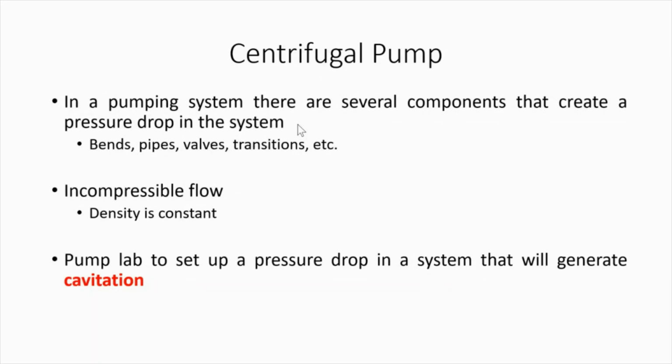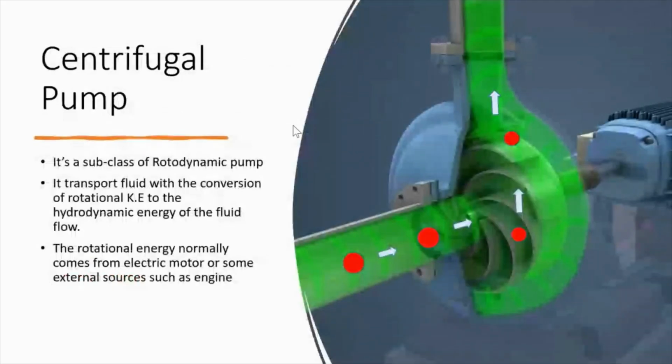before getting into that, I think Carlos has a question. He's asking, so the blades scoop the water? He corrected himself. No, the blades don't scoop the water. The blades don't create a vacuum or pressure drop. What they do is just put kinetic energy into the fluid. That's how the fluid moves.